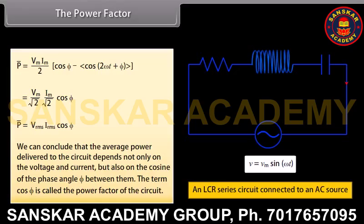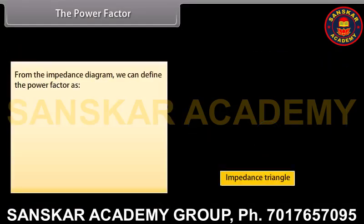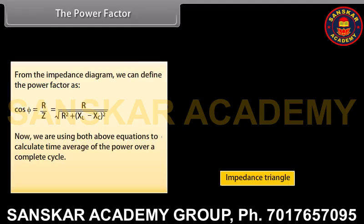We can conclude that the average power delivered to the circuit depends not only on the voltage and current, but also on the cosine of the phase angle phi between them. The term cos phi is called the power factor of the circuit. From the impedance diagram, we can define the power factor as cos phi is equal to R upon Z, which is equal to R upon under root R square plus XL minus XC square. Now, we are using both above equations to calculate time average of the power over the complete cycle. P bar is equal to the product of Irms square and R.